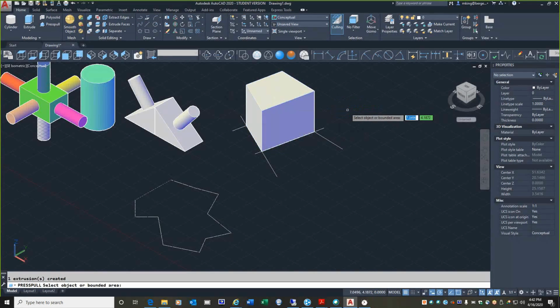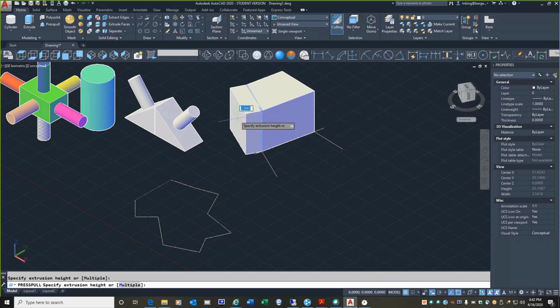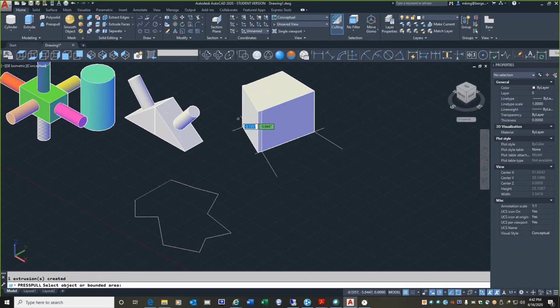Okay, easy as that. And what's also kind of neat is, let's say I realize I need to build outward from this shape. I need to build out, let's say, a 1/2 inch. If I put my mouse anywhere within that face and click, and I move outward, I could say 0.5 enter. And that's not very big, right, compared to 6 inches tall. Okay, so I can add to existing shapes, which is kind of neat.